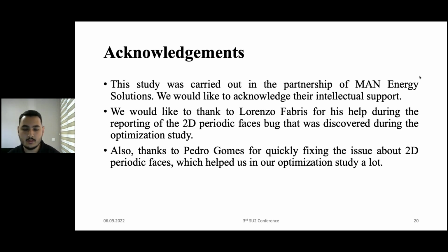We didn't really do anything special for that point. We used the same methodology for every point. So if I understand correctly, you started from the design point and you slightly change the back pressure. Could you repeat? No, I couldn't, sorry. So did you change the back pressure? Yeah, so did you modify the back pressure at the compressor? The way we simulated for different operating points was by changing the outlet pressure.